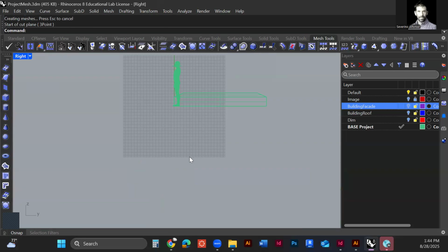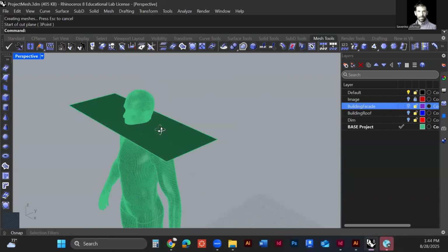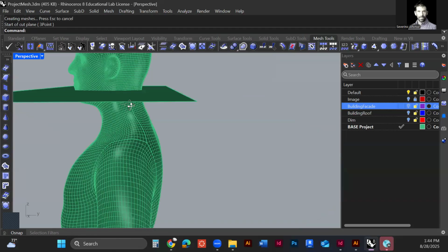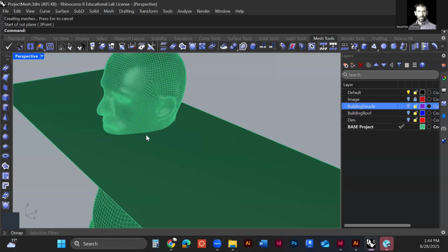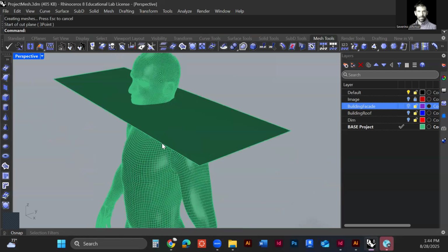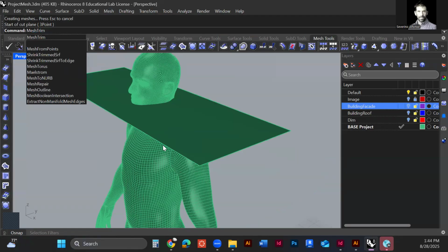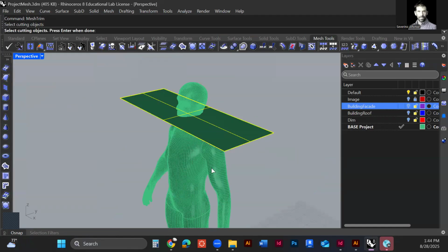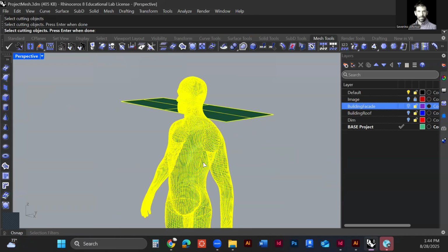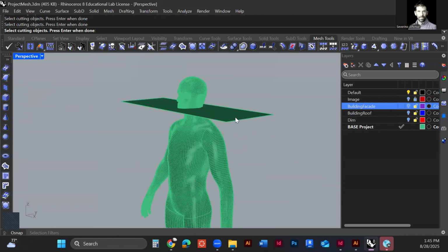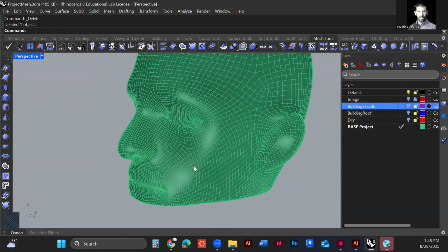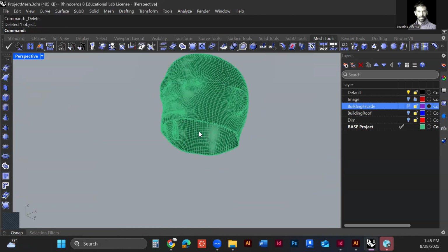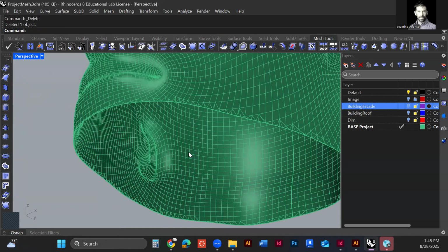So what that does is just a plane that cuts the geometry you have selected. So it just understands the boundaries of that object and it just creates a plane. I'm going to use the mesh trim command. Select the form that we want to use to trim and then select the form. Try that, enter. So that gives me this piece, which, it's okay, nice.